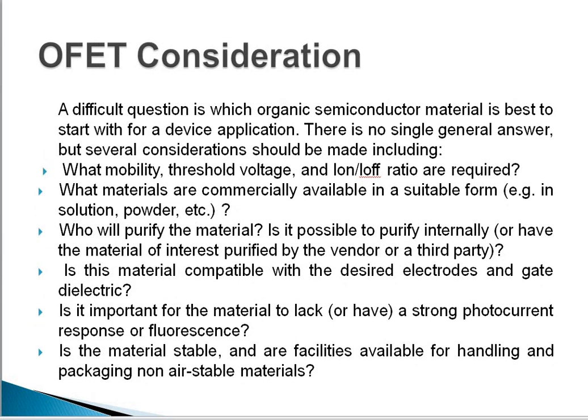Organic field effect transistors have unique material properties, which both make them attractive as a material system and somewhat complicated to handle. A difficult question is which organic semiconductor material is best to start with for a device application. There is no single answer for that, but several considerations should be made, including: first, what mobility, threshold voltage, and on-off ratio are required.